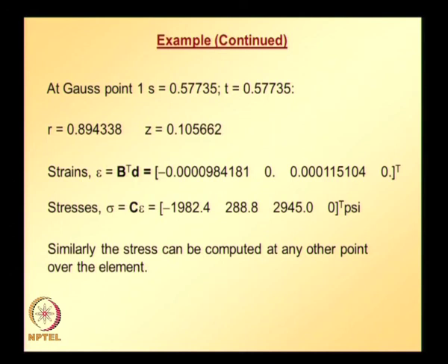So basically, as a part of axisymmetric elasticity problems, we looked at the governing equations for axisymmetric problems, and also the derivation of the element stiffness matrix and equivalent nodal load vector for the linear triangular element and also the 4 node quadrilateral element. Similar element stiffness matrix equations and equivalent nodal load vector equations can be derived for higher order elements such as the 8 node serendipity element, following similar steps. So, in the next class we will continue with 3D elasticity problems.